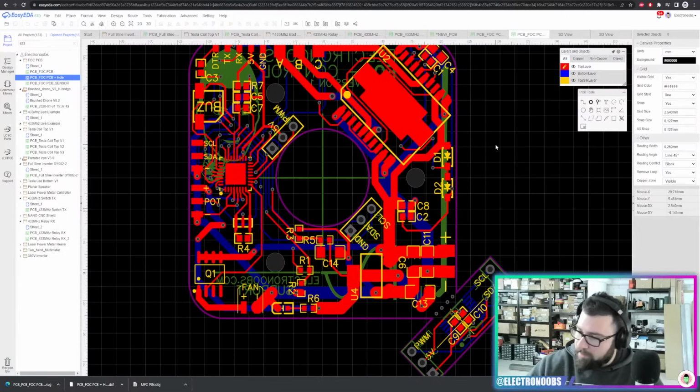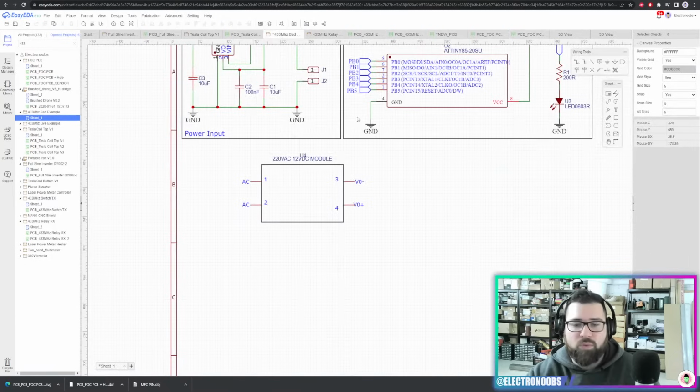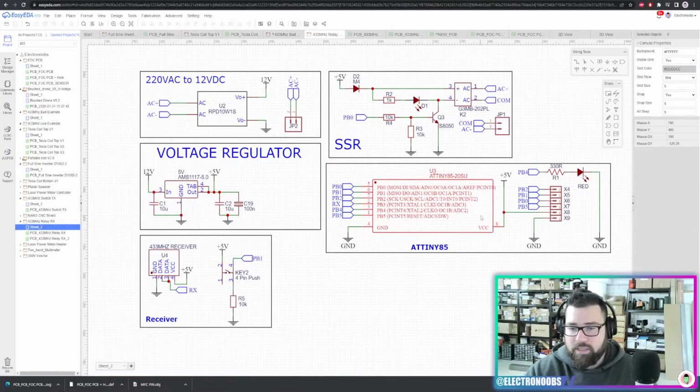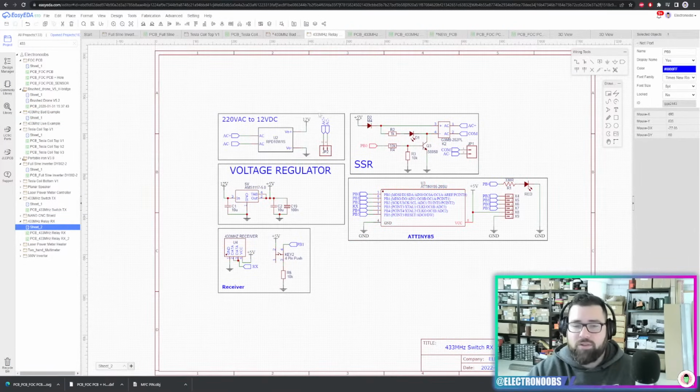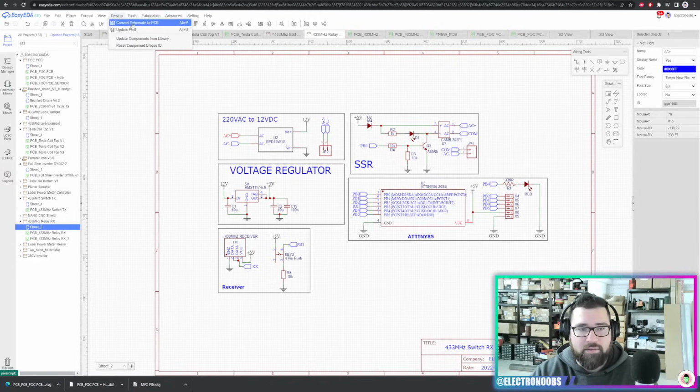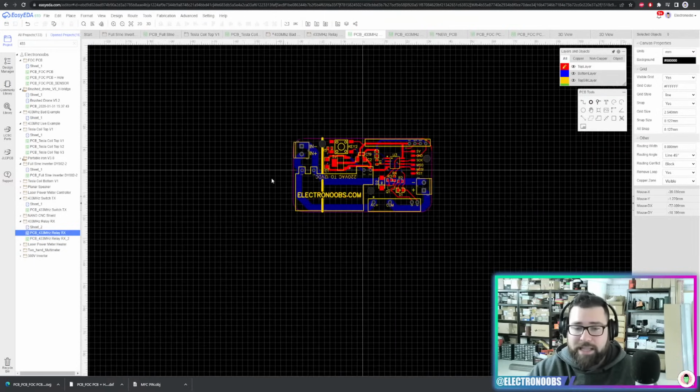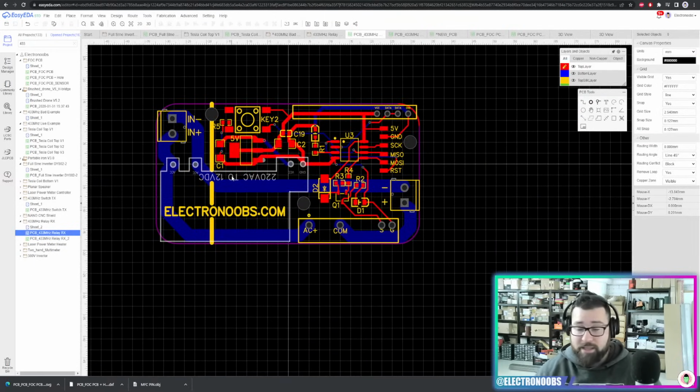You make a prototype. If the prototype works, you can pass that final schematic from drawings with your pencil to EasyEDA. It should be something like this. This will be the final schematic. Please use these kind of connections. You make the schematic, then you go to design, convert to schematic. You select the position of each component more or less. This has to have some logic because the inputs are on the outside, the microcontrollers in the middle, the voltage regulators should be close to the input of the power, and so on.